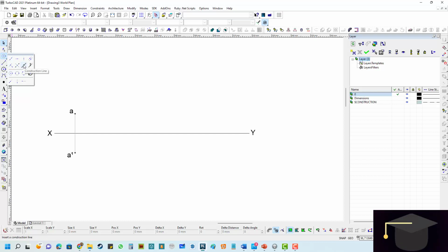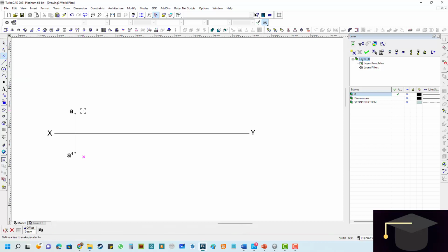It doesn't matter, you decide, but let's use, just for the sake of it, the parallel line tool in this case. Click on that line and make sure that when we click on it, you choose the one that is discoloring, and that will be parallel to that line that we want. And I drag my mouse to the orientation of where I want to place it, and I keep my eye on the offset here at the bottom of the screen.